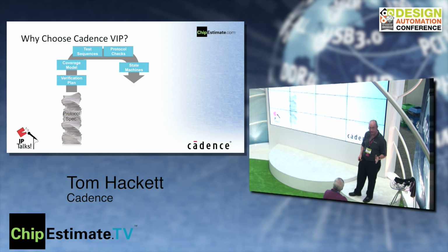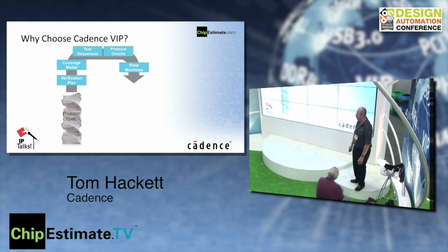It's enormous. And so if you're going to create essentially advanced simulation models to play against your design, let's say your design has a root complex, and you want a PCI Express endpoint to test against it, then you're going to have to sort through those 1,000 pages and create a simulation model, which is verification IP. And that model needs to have these different things to be useful. It's got to have all the state machines that are specified in the protocol spec. And these state machines can get pretty complex, especially since everybody is making their state machines more complex to add additional types of low power states. You might have 3 different low power states you have to deal with.